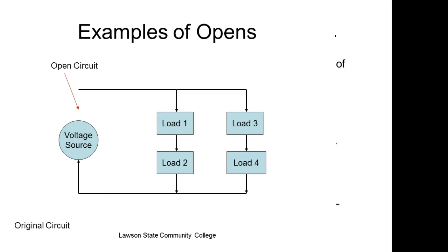So you get into your house and some of your outlets stopped working. Something like that just happened to me. My wife turned on her air fryer the other day and it stopped working. And then we noticed the plugs in line with it stopped working, but everything below that didn't. What had happened, one of the wires on one of the terminals in one of the outlets had come loose, and everything down below that stopped.